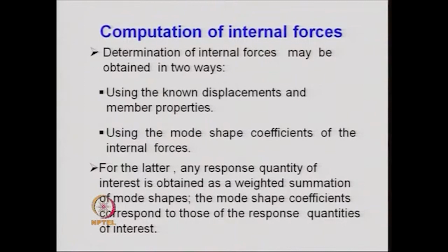So, the mode acceleration technique is found to provide better results for any kind of response, be it the bending moment, shear force, drift, or whatever response quantity you want.